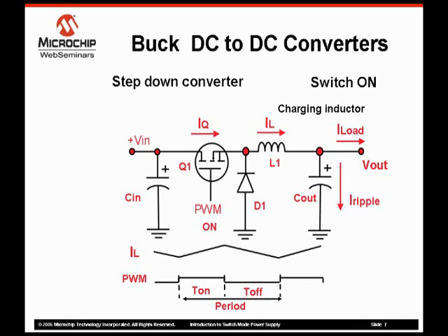The inductor L1 controls the current flow. The applied voltage across the inductor causes the current to increase linearly with time. Think of this process as charging up the inductor. The inductor current flow charges the output capacitor, which raises the output voltage.